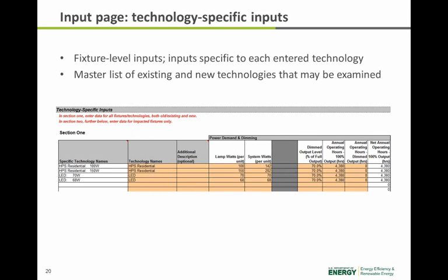So again, Doug, I was queuing up a question for you. In the tool, why do we have a cost for maintenance for the LED fixtures? Well, although there's very likely very little to no scheduled maintenance, there's still the possibility of rare failures of a fixture that would require spot replacement. Additionally, there may be minor, rare scheduled maintenance for cleaning the fixture.